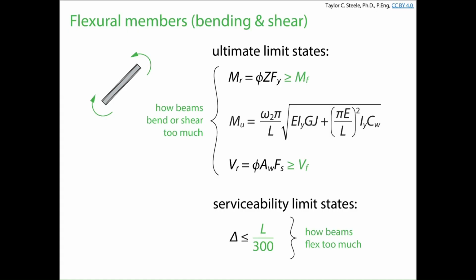The other day, we started talking about what can happen when beams are not laterally braced at the compression flange. And so if a beam is laterally unbraced along the full length, it can experience something called lateral torsional buckling. And this lateral torsional buckling is an elastic buckling mode. It's very similar to the Euler elastic buckling load, and that's going to reduce the moment resistance. And we looked at this curve where for short beams, if the unbraced segment length was really short, we get plastic moment. For intermediate beams, we get sort of an inelastic lateral torsional buckling, and for long unbraced segments, we get elastic lateral torsional buckling.